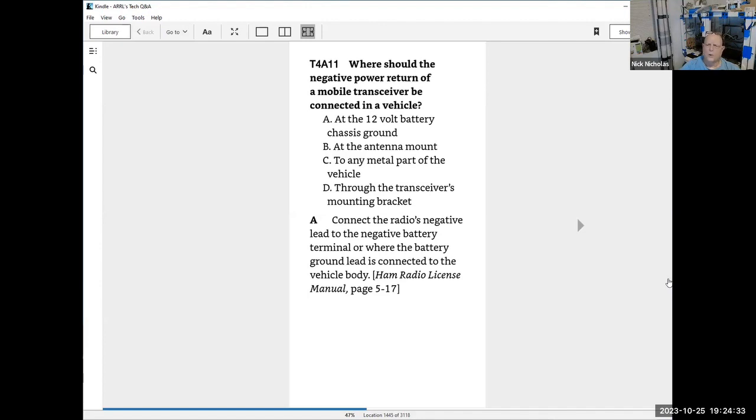So you'll pick up noise. Two, as good as the guys who work on the line are that build those cars, not every one of them had a perfect day where every single bolt, every single weld, every single connection was perfect. So the body is not a reliable return path for the electrical for a radio, especially one carrying enough power for like a 30 or 50-watt transmitter.